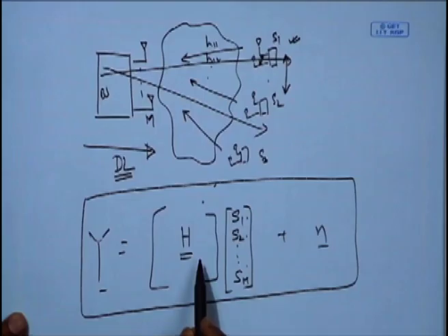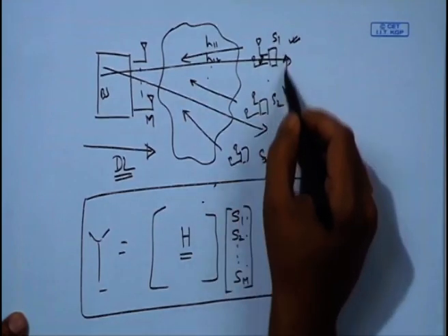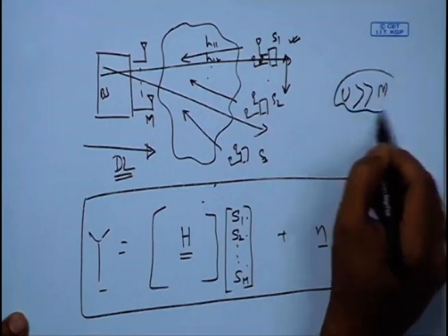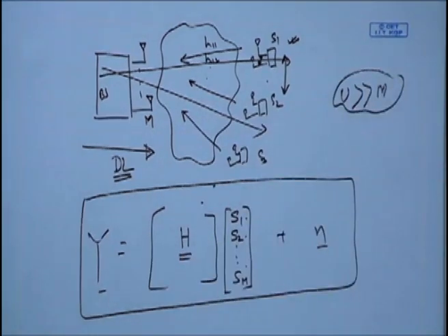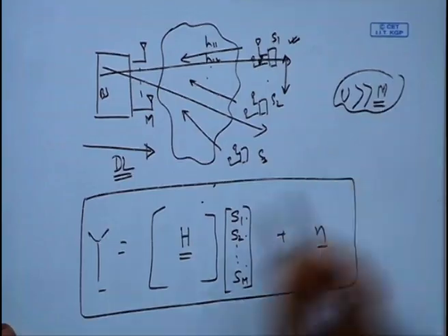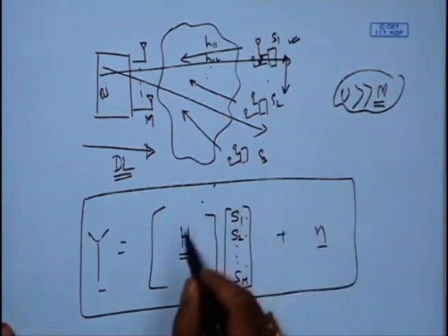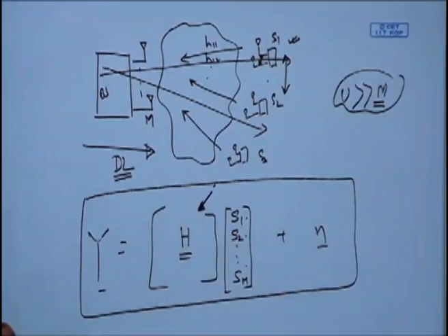So in this case, what I would like to point out, you can easily guess, is that usually the number of users in the system is much larger than m. M is the number of transmit antennas. So if we have to choose at most m users, then we have to choose those m users which would result in an orthogonal channel, because if we can get an orthogonal channel, we have a very simple receiver to implement. Otherwise, our receiver architecture would be difficult.